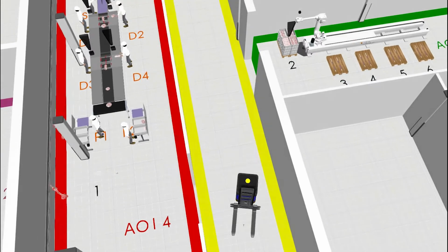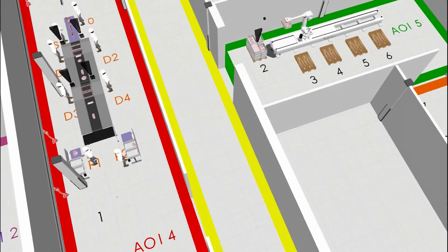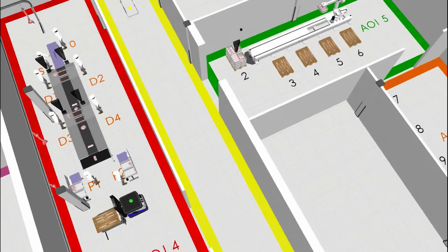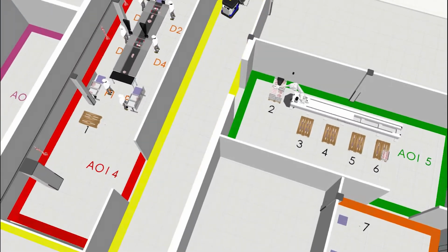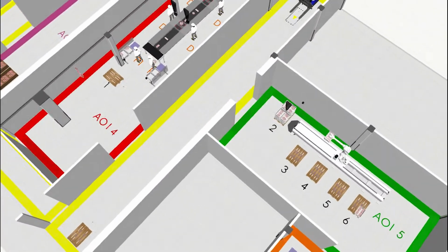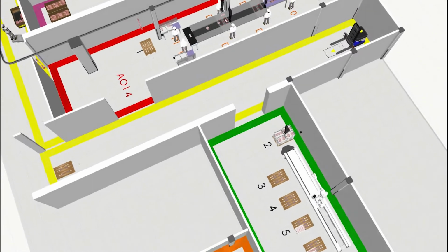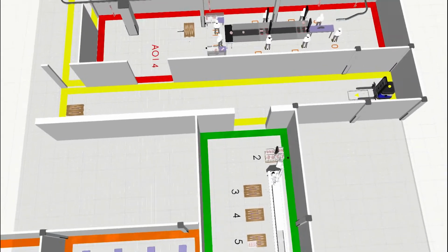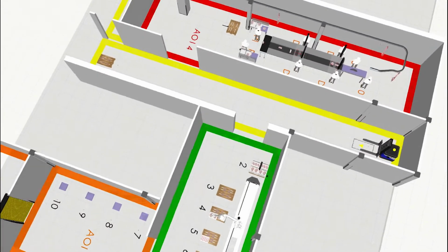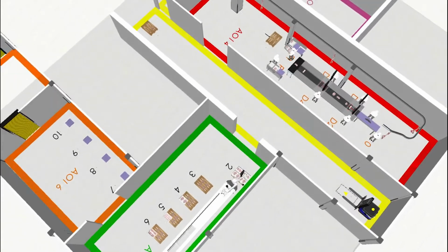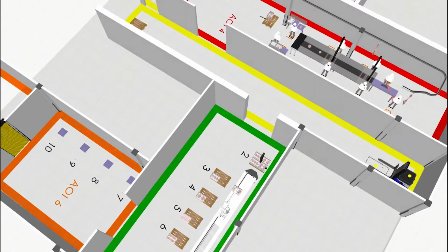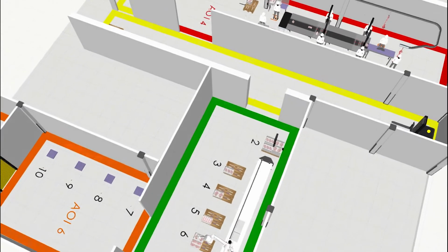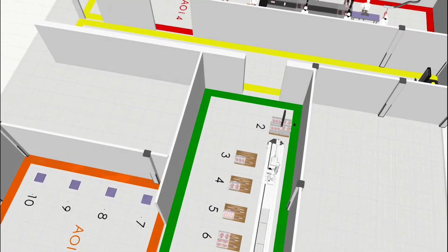ERP software receives the information and sends back information to the robot arm to place that box on the pallet that is on position 2. 1 pallet can stack 4 meat boxes on 1 horizontal level. A meat box filled with meat can weigh around 30 kilograms maximum. Thus, based on the load and workspace requirement, a robotic arm IRB 4600 from ABB is selected. In terms of precision and repeatability, this robotic arm fulfills the requirement for this operation.